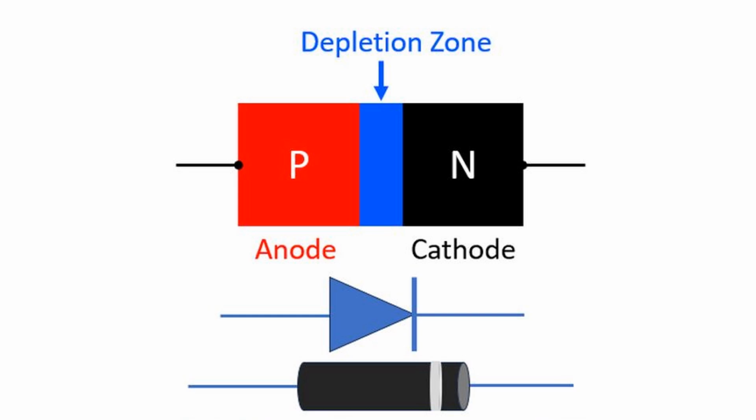In the reverse bias situation, no current flows across the PN junction. That is how a semiconductor diode functions as a rectifier, converting alternating current into pulsating direct current as it cuts off one half of the AC.